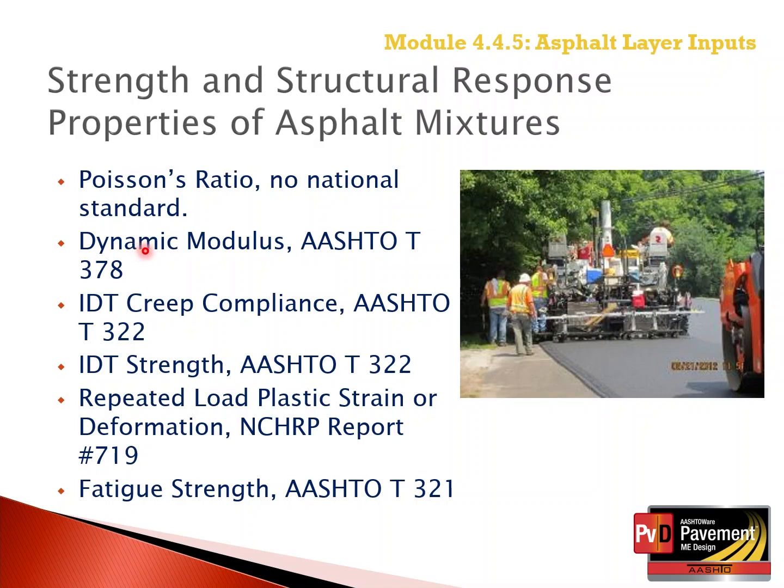The dynamic modulus values are measured in accordance with AASHTO T378. The indirect tensile creep compliance and strength values are measured in accordance with AASHTO T322. Both the creep compliance and strength are measured in accordance with AASHTO T322.